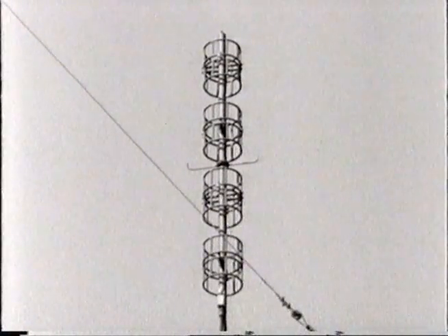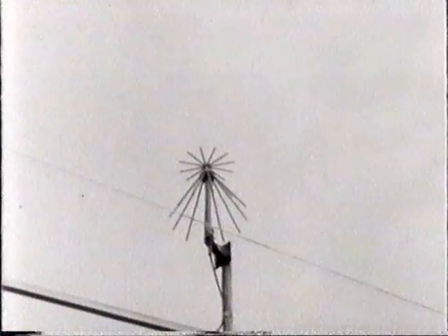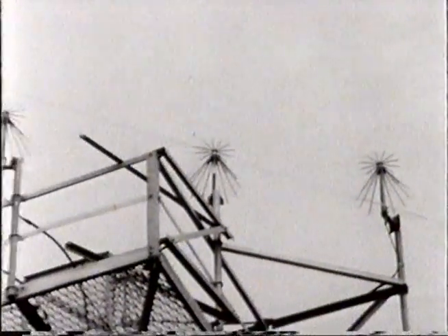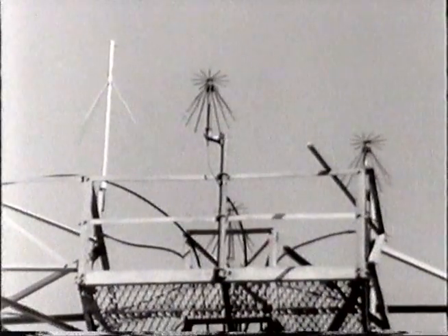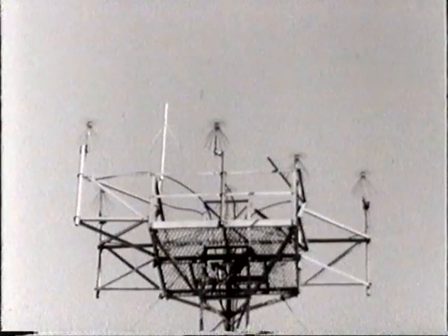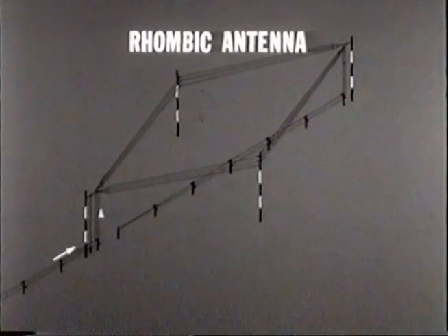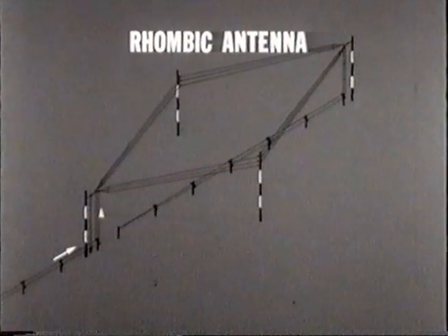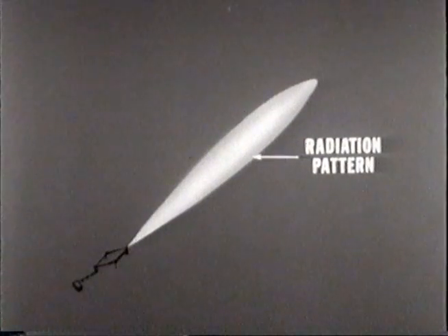For air-ground communication, the HF antenna is gradually being replaced by these very high-frequency antennas. Perhaps the greatest advantages of VHF are freedom from static and smaller antennas. These ultra-high frequency antennas have the same general advantages as VHF.